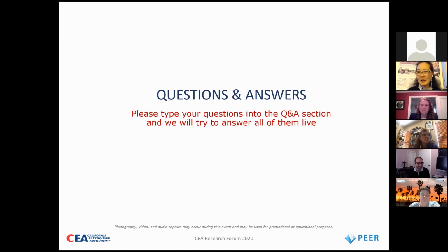Farzin, for the loading protocol, does the single loading protocol used replicate the near fault impulse loading as well as the ordinary far field loading? Can you help us address that? Sure. I touched on this issue during the presentation. Going back to the work that Tara and Chai did at Davis, they compared the impact of a near field loading protocol with a far field loading protocol, and there was not that much difference between them.